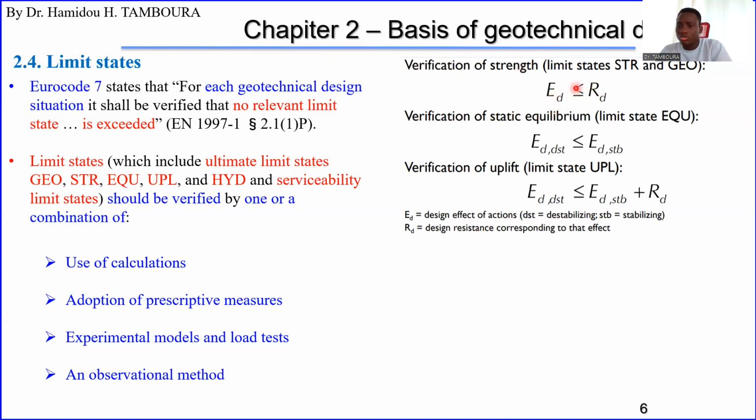Ed should be less than Rd, and this Ed here means design effect of action. Design effect of action means there are some actions, like force, for example. Forces are loads. So what will be the effect of these actions, these loads? Okay. And this Rd is design resistance.